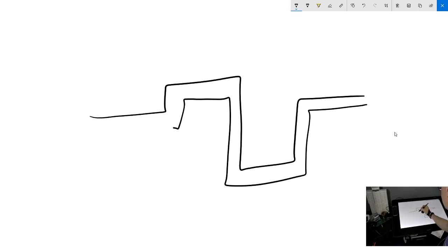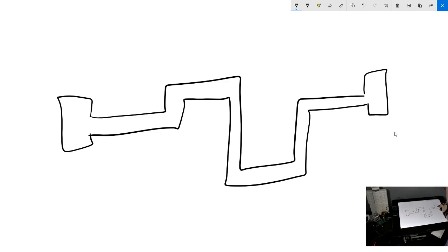You're going to see kind of a wavy line like that, and then there's going to be a connection over here and a connection over here. So that's one type of resistor. Basically, these resistors are measured in squares, and each square gives you another incremental unit of resistance. And in fact, resistance on chips is measured in ohms per square.